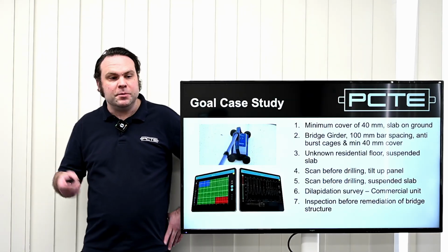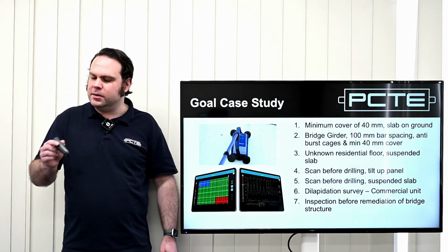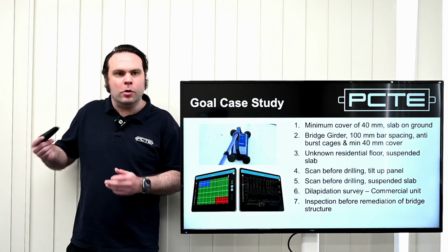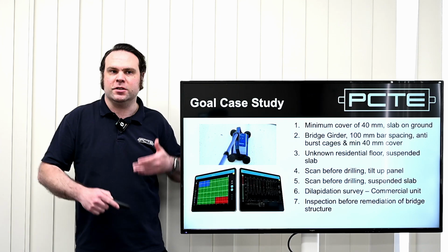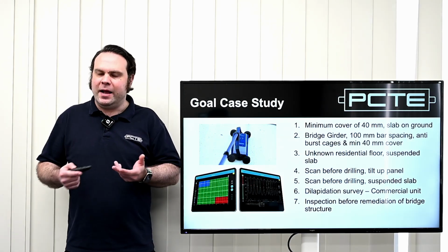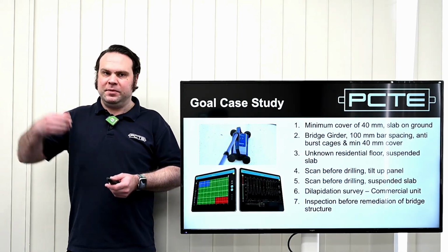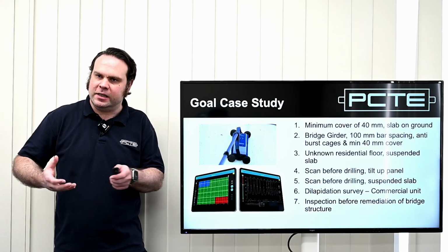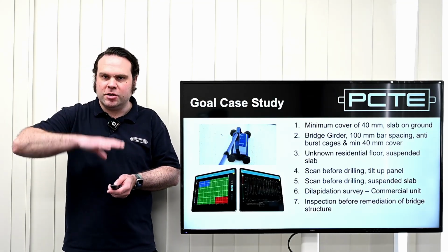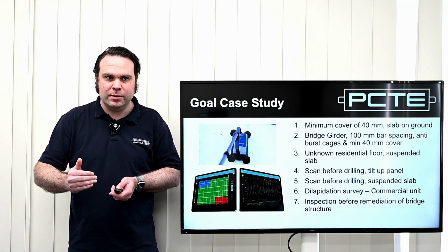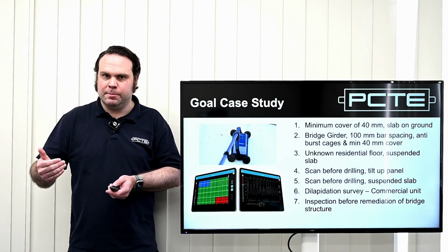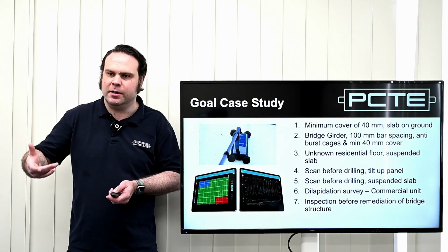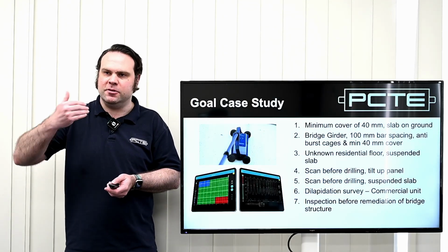Yep. The reason that I do highlight cover meters for dilapidation or remediation is that durability aspect. When we do our half cell potential and our corrosion discussion this afternoon, we're going to talk about a lot of things that tell us, is the steel rusting, or how quickly is it rusting, or what's the concrete like. But an underappreciated part of a durability assessment is how deep are the bars and where is the salt or the contaminants, how far have they diffused in.